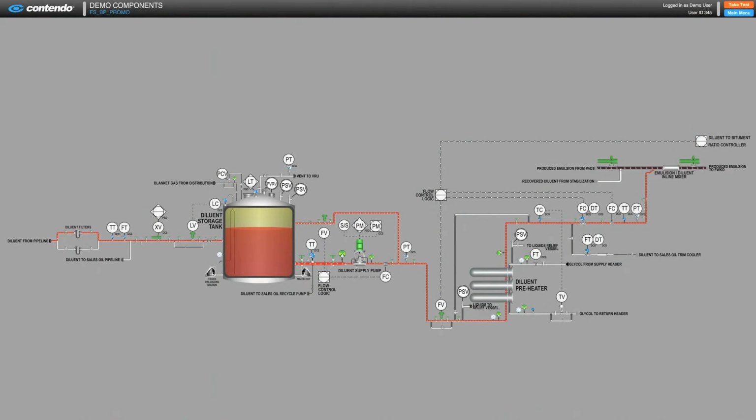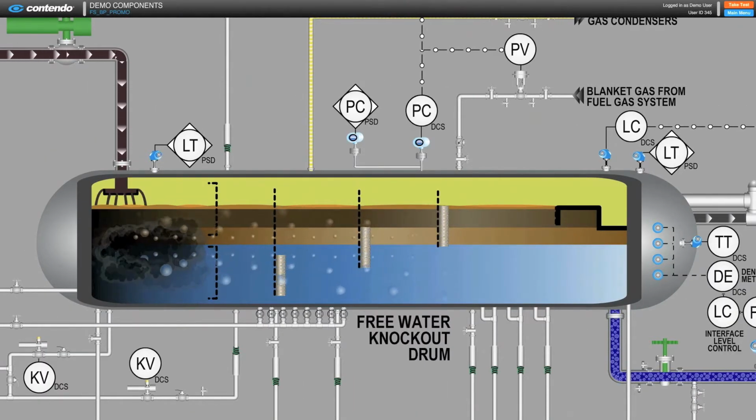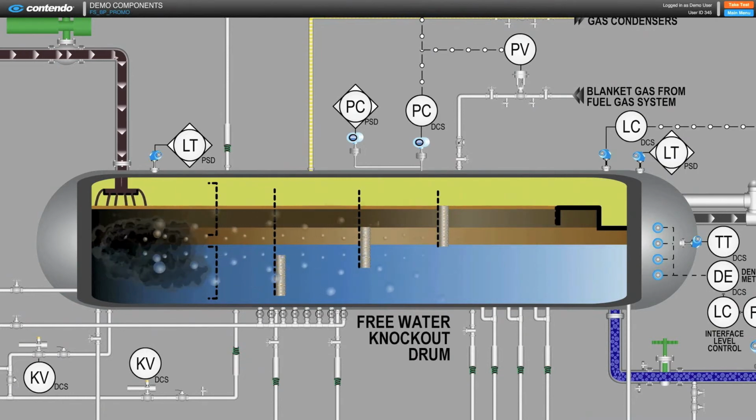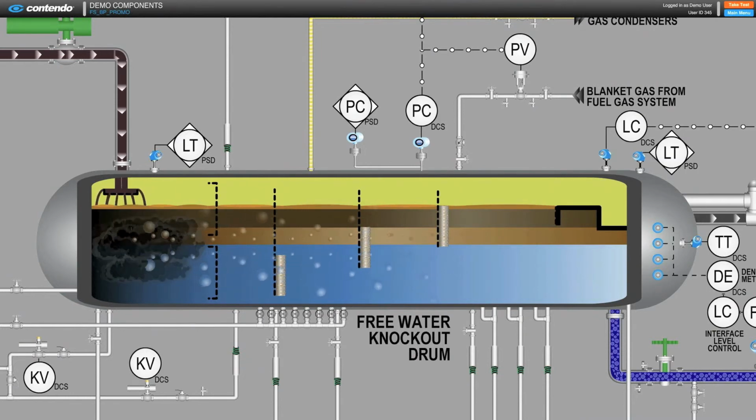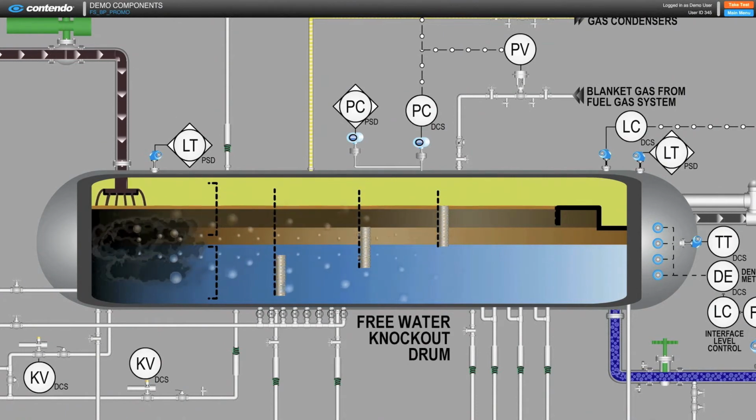We use a combination of narrated animations, text, and other visuals to demonstrate how a process operates. We start with diluent heating and injection into the produced emulsion for density adjustment of the bitumen. We follow the produced emulsion through the bitumen inlet section of a SAGD central processing facility where bulk separation of oil and water occurs in a free water knockout.